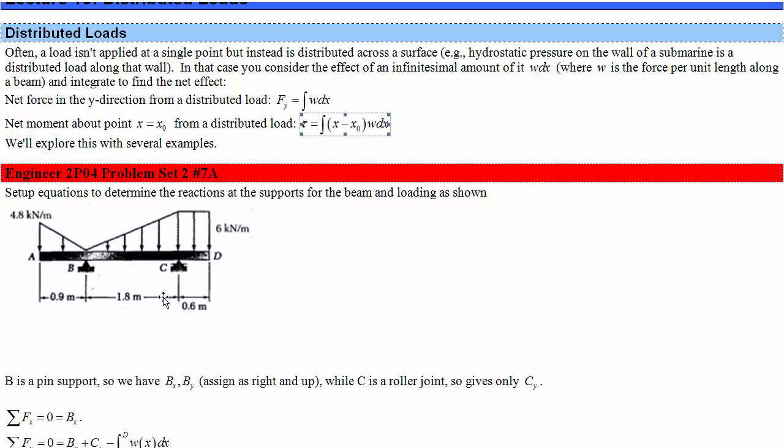So we're going to have an easier time if we find the torque about B, because this is a 0 point for these lines. So you know how the equation of a line is y equals mx plus b? If you pick an origin so that the line goes through that origin, then the y-intercept is 0, and you can just get rid of the b. It's just y equals mx. Conveniently, by picking that as our 0 point, also the torque formula just becomes the integral of x times w dx. Okay, so let's find out what some of these w's are.